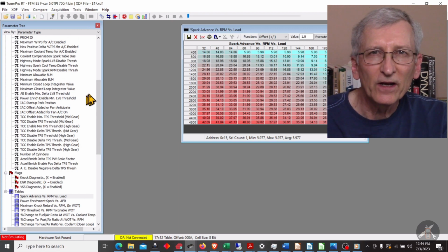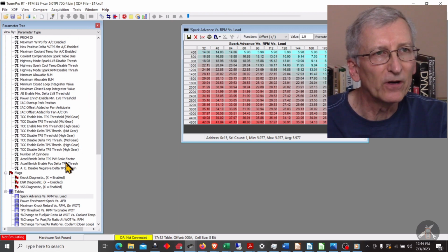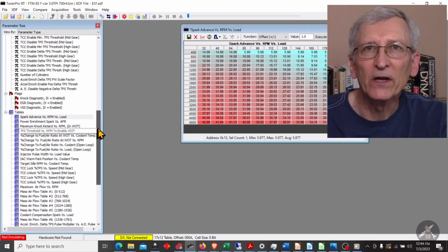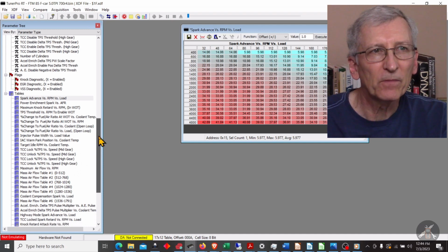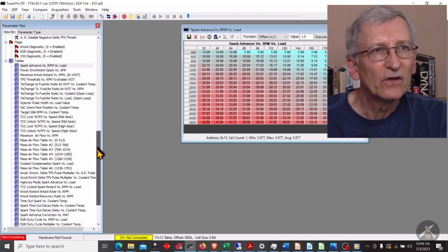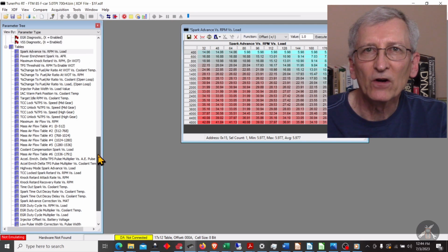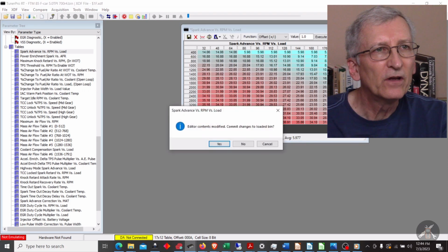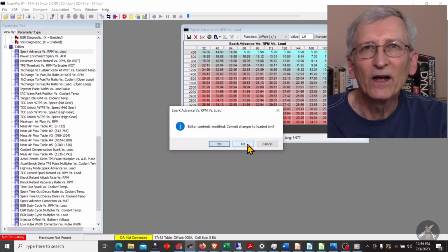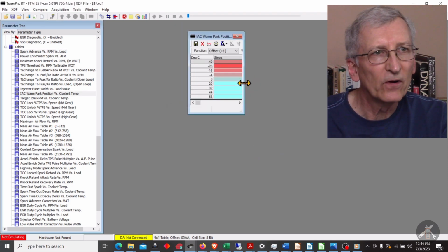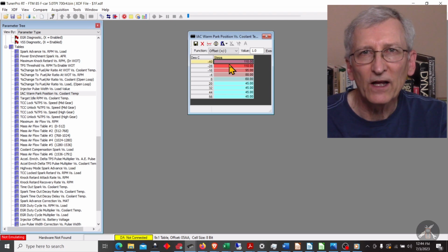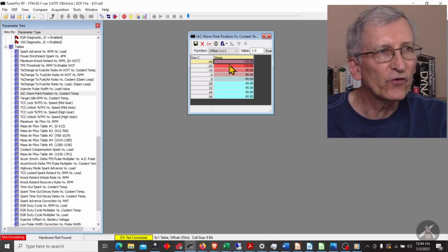Also, one thing I found that kind of threw me off for a minute in version 5 here, it looks like this table I got, IAC warm park position, looks blank, but it really isn't blank. The box just pops up kind of narrow, and so if it's minus 40, they're going to have the IAC open farther than if it's hot. If you're at 50 degrees C, the IAC setting will be a lot lower in steps. So this is where all the data is.